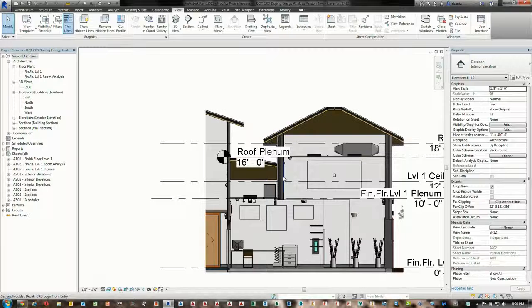But if we're concerned about, I really want to model my Revit MEP building, then use features like Copy Monitor. Copy monitor all the walls, the levels, everything you can, and build what you need to build. Ceilings, roofs, even if necessary, reference planes, and get all of your spaces set up properly, get all of your zones set up properly. And once it's tight, then run the analysis.